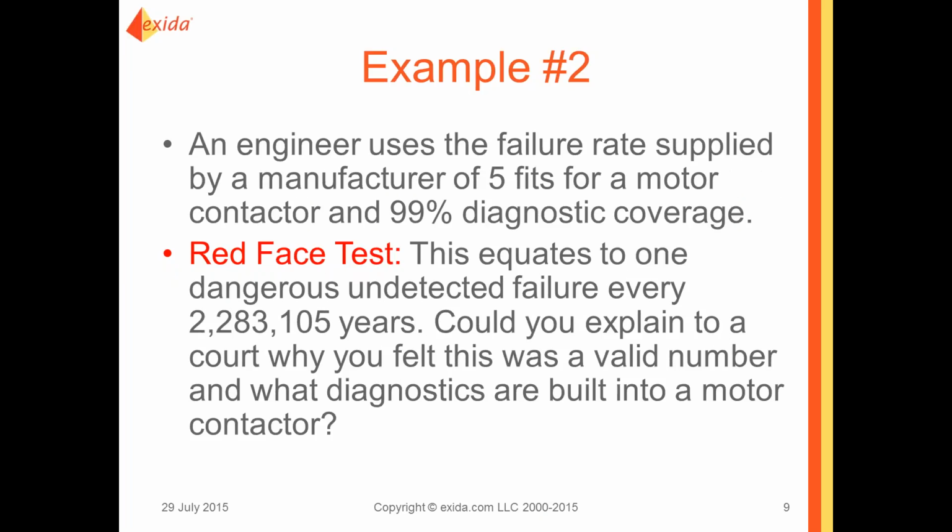Example 2. An engineer uses a failure rate supplied by a manufacturer that states a motor contactor has a total dangerous failure rate of 5 FITs and 99% diagnostic coverage. This equates to one dangerous undetected failure every 2.2 million years. That means if you had 2.2 million motor contactors in service, you would expect only one dangerous failure per year that wasn't detected by an automatic diagnostic.